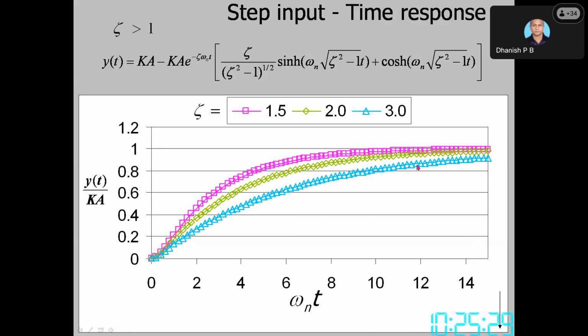Okay, so we want our measuring instrument to show the correct reading at the earliest. But a high damping means, so sometimes you might have seen speedometers in buses. Of course, now most of them have become digital, but the old speedometers, it will keep on increasing as if it's not reached the final value. This is the response of an overdamped system to a step input. You are given a step, but it does not reach the step immediately, but reaches the final value after a long time.